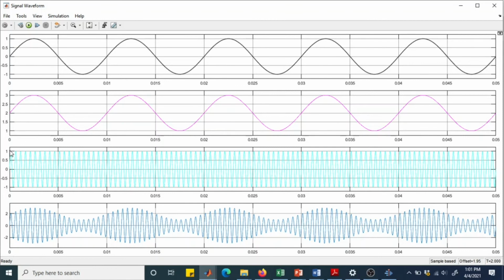The carrier is operating at a higher frequency, this is at 2 kilohertz. And finally, if we modulate this signal with this signal, now we have the amplitude modulated signal. And the important thing is that we have given enough DC offset that the lower value is above 0. So right now the maximum is at +3 and the minimum is at +1. On the lower side of the envelope, -1 and -3. So we do not have the zero crossing of envelope. It is always positive.